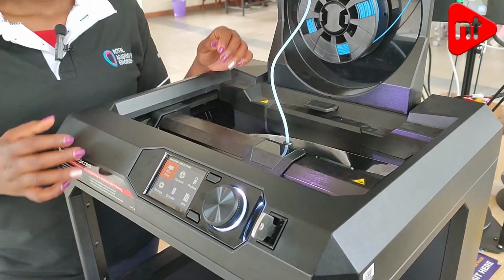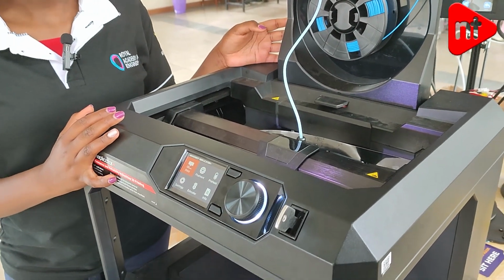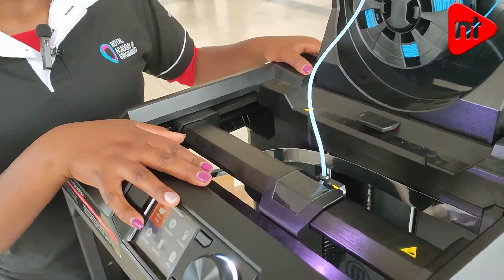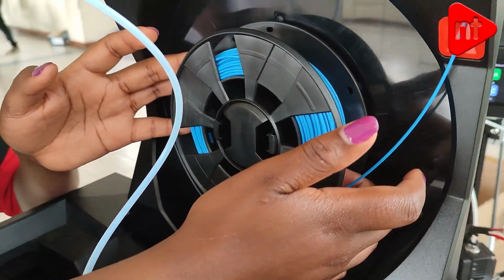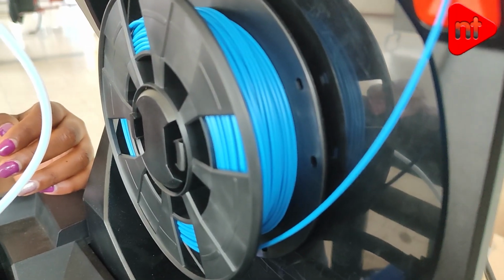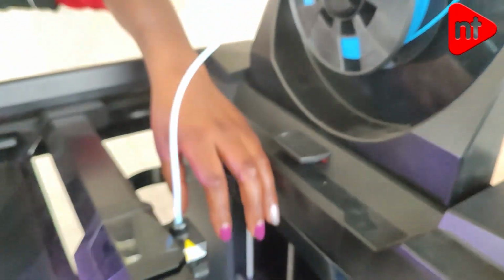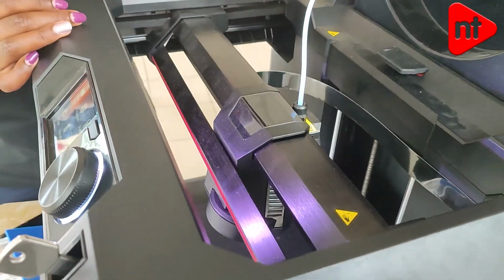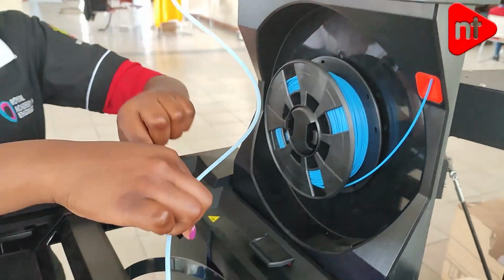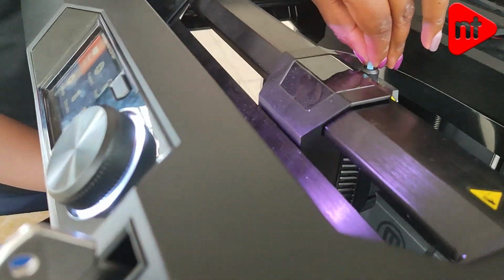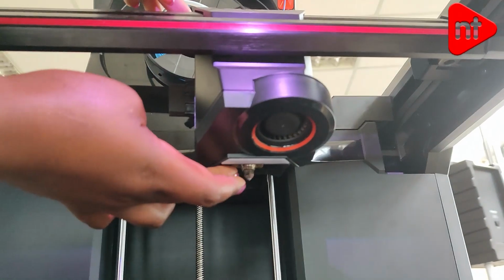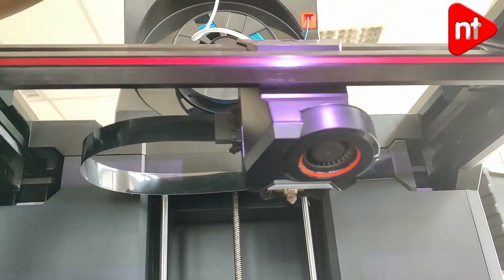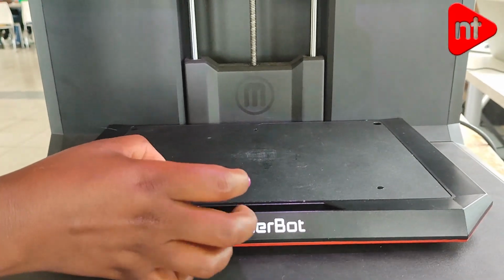Yes. So the 3D printer basically is made up of some parts that are very essential. If you look at this one, we have this part that looks like some plastic wires. Basically, this is what we call the filament, which is the material the 3D printer uses to print. Then we have the extruder. The filament passes through this piping going on to the extruder, and this extruder has a pointer below here which heats up, melts the plastic, and then the plastic is deposited on the build plate. It is attached to the build plate such that it builds your item as it is going up.